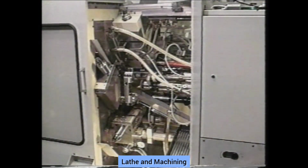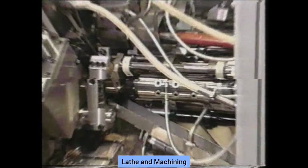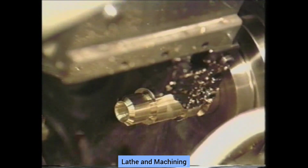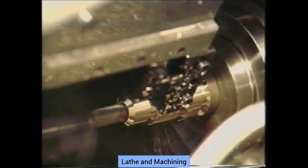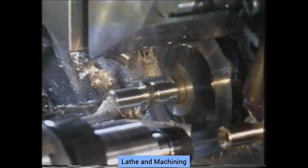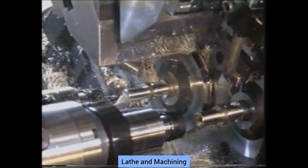The multi-spindle automatic is the premier high production turning machine. It can machine multiple parts simultaneously with multiple spindles. The 6 or 8 spindles are held in a rotating spindle drum. This drum rotates the spindles to the cutting tools positioned on slides.